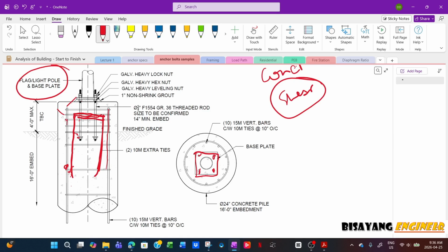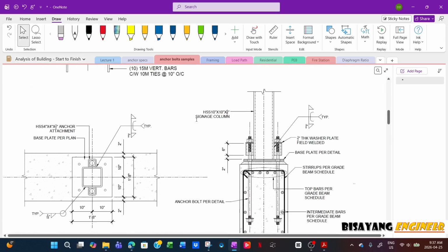The same as if you have a tension bar in a beam, or you need to splice, then you have to determine the tension on that joint, and make sure that the lap is sufficient to transfer that load. So that's the same condition.